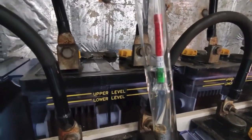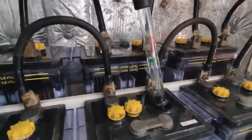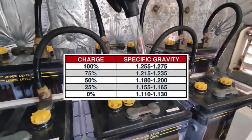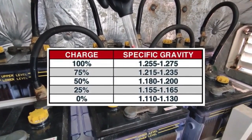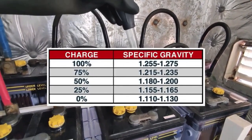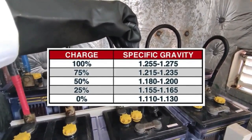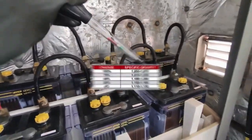Now note that IEEE standard 1188, which is the recommended practice for maintenance, testing, and replacement of valve-regulated lead-acid batteries for stationary application, states periodic equalizing is not normally required to correct cell unit imbalance. Equalized charging should not be performed unless specifically recommended by the manufacturer.